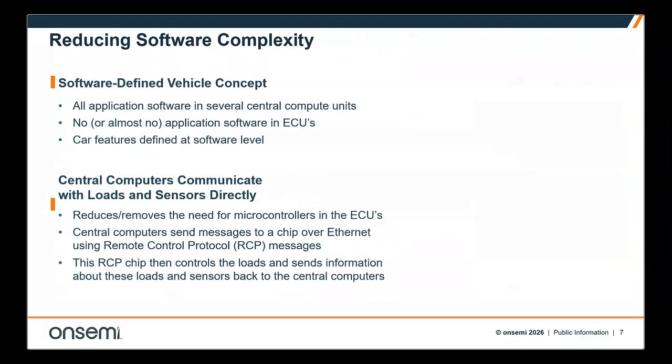The software-defined vehicle concept is the other major enabler for zonal architecture. The idea is quite straightforward. We need to consolidate all application software into a small number of central compute units, removing the need for application code in each individual ECU. This means car features are defined at the software level, which enables over-the-air updates and post-sales customization, for example, and it reduces or removes the need for microcontrollers at the edge.